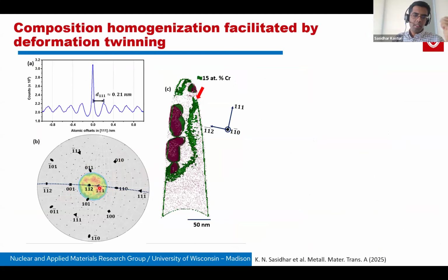We had to find another low Miller index crystallographic pole at an angular separation of 20 degrees to 111, and the crystallographic directions that meet all these requirements give an orientation shown here. So this is where the 111 lies, and here is 112, bar 1, bar 12.